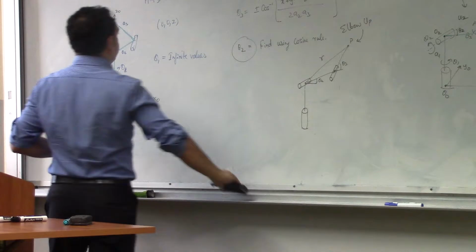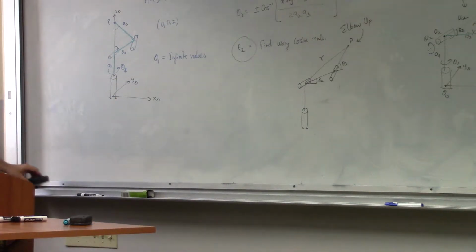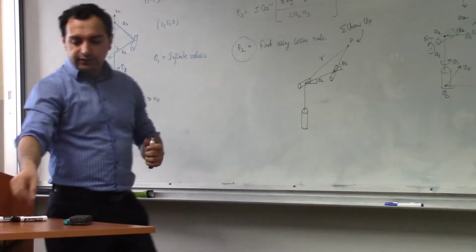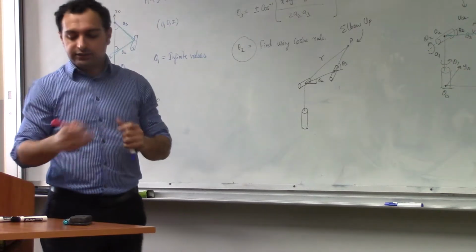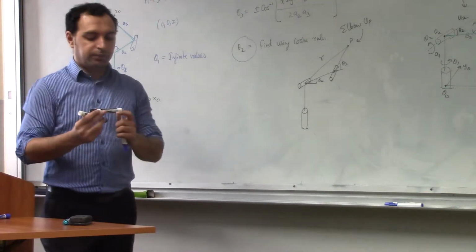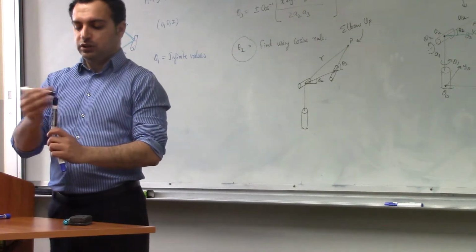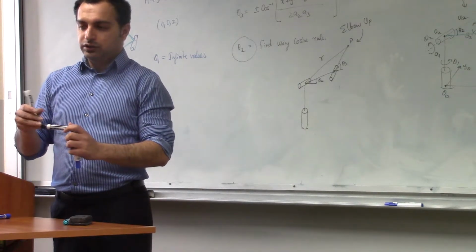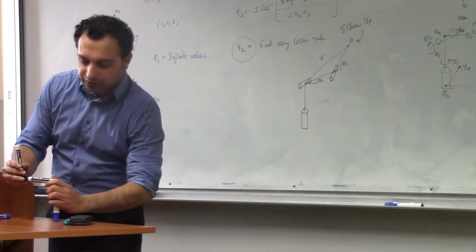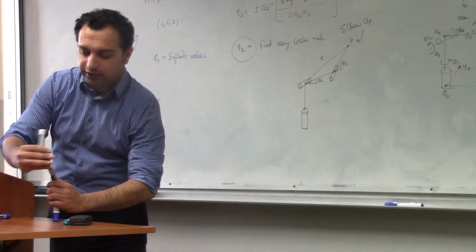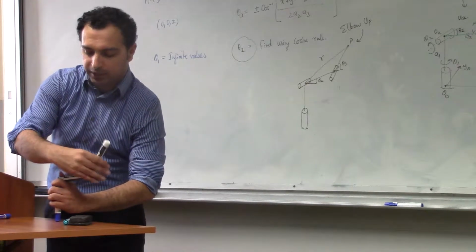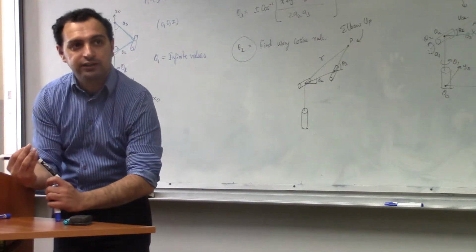So you have to look at some special cases. Another thing is, let's say that I have the manipulator like this, and I'm trying to reach this point, right? Now I can reach it with this value of theta, or I can completely go here by pi by 2 and then fold over like this, okay?